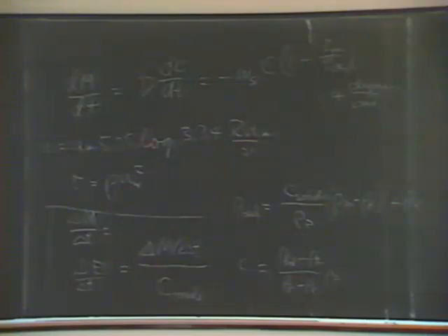We're invariably dealing with a current that reverses, which means that it stops and picks up again. And during the times that it's moving slowly, material will deposit if it's in suspension. So you want to be able to move that back out. To do that, you provide shear stresses on the bed that will move it out at least once a day, at least once during every tidal cycle.